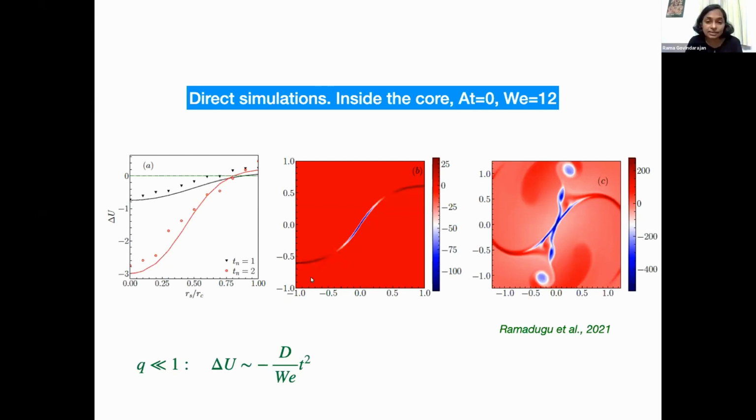And this is at shorter time, and at longer time, it just goes Kelvin-Helmholtz unstable, and then due to the action of viscosity, this newly generated vorticity peels off from the interface. So remember that even though you're going Kelvin-Helmholtz unstable, surface tension simply hates that, and at some time or other, it's going to make the interface straight. But then the vorticity thus generated is going to peel off. So even if the interfaces come back to this shape, there's vorticity peeling off. So we see that this mechanism is active.